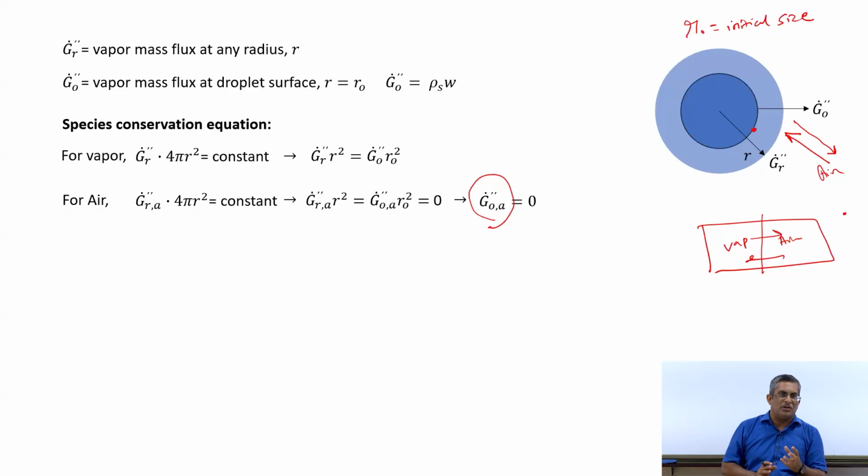And that is the reason why if you put a water droplet here, it vaporizes, okay, even if the water temperature is not equal to the boiling point temperature of water. Okay. This is evaporation which can take place at any temperature below the saturation temperature. Okay. But you imagine the relative humidity of this room is 100%, and then you do the same experiment, that is you bring a droplet and keep it. Will it evaporate? Answer is no, because the gradient is 0.